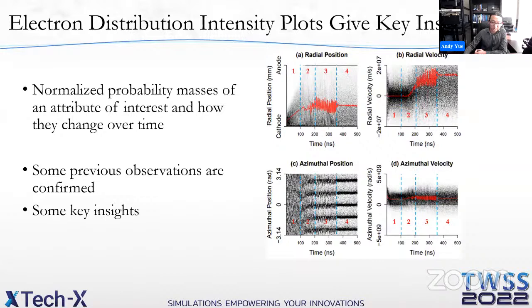In this plot, we can clearly see the pi mode pattern emerging out of chaos. The fuzzy lines in region 3 indicate frequency instability, which confirms our previous observation that we have mode competition in the system during that regime. And the lines in region 4 are quite clean, indicating the frequency is stable. The azimuthal position plots, given the appropriate data dump period, function as a great diagnostic for frequency and phase stability.